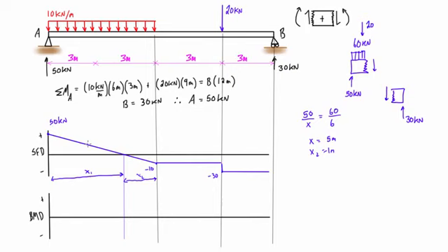Now, you could have just eyeballed this one because it's a little bit easier to see, but often it's not that easy, and quickly doing this will be the most foolproof way of finding the x location. So we're going to use that information to find this area in here. The area of this triangle is 1/2 base times height, which is 1/2 times 5 times 50, which is equal to 125.